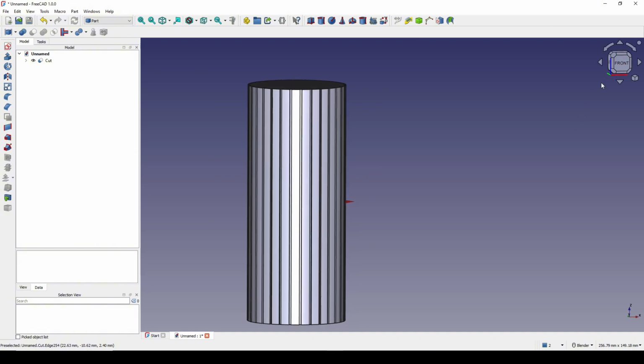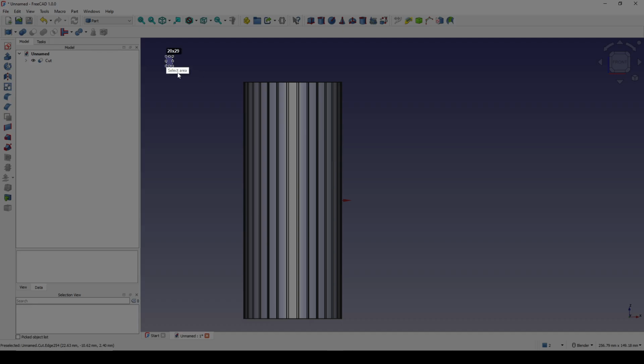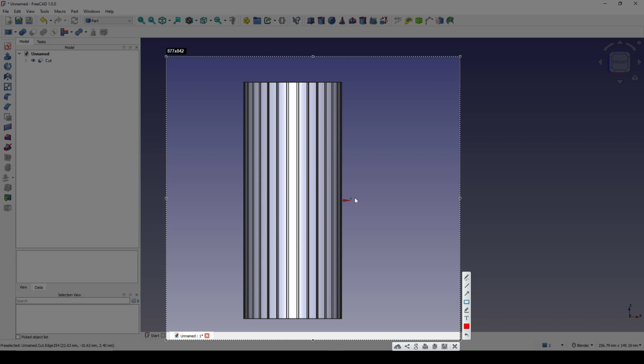The next step is I want to cut in between this cylinder, and after I cut that, I will have one surface up here and one surface down here, and I will use these two surfaces and I will revolve to generate the geometry shape like this.